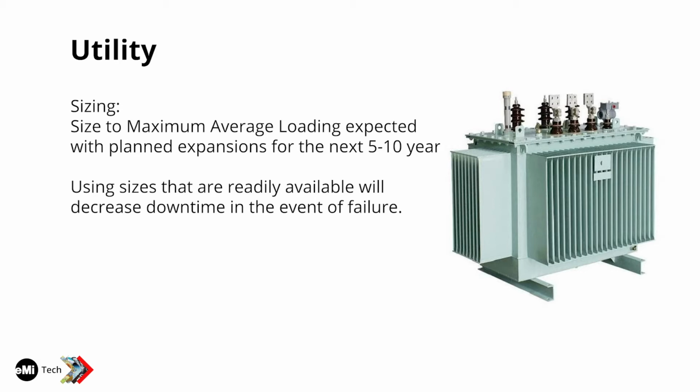Some countries, like if you ask for, I don't know, a 400 kVA transformer, it's going to take you 3 months of feet dragging to get it. Whereas if it's 100 kVA, oh, we have 10 of those in our warehouse all the time to replace. So it's good if you can pick ones that, when you talk to the utility, that's important. If you're on a site, if you can talk to the utility, ask them what their common sizes are, because that way if one fails, they can easily swap one in.